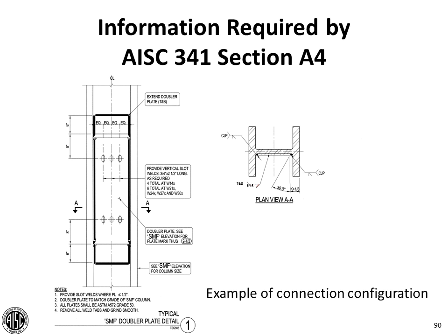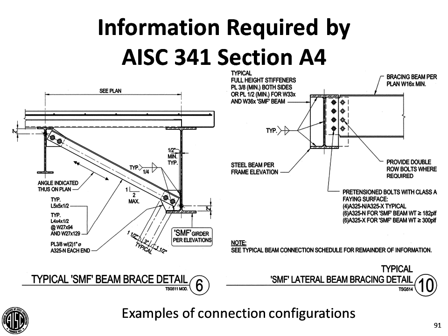Showing welding that would be required to attach the doubler plate to the column flange, both at the inside of the column flange along the top, and if necessary through the use of plug welds in order to deal with the plate and web slenderness requirements that are specified in 341. Here's an example of the bracing detail that might be required if the framing is parallel to your frame member or is perpendicular to your frame member.